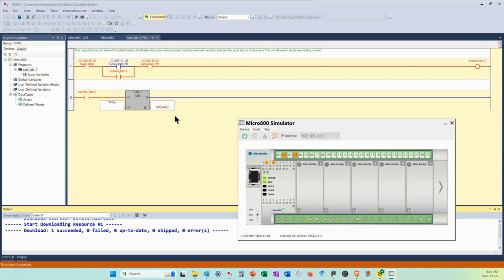Notice it does it in milliseconds, and notice how it seems to be jumping. It's not like you're seeing 9, 10, 11, 12. It's kind of jumping all over the place. The scan time on the processors is very, very fast. By the time the scan sends its information and it gets to the PC from the PLC, and Windows has had its time with it, as far as the processor and process is concerned, you're looking at ancient history. Okay, so this has now set our 15 seconds.